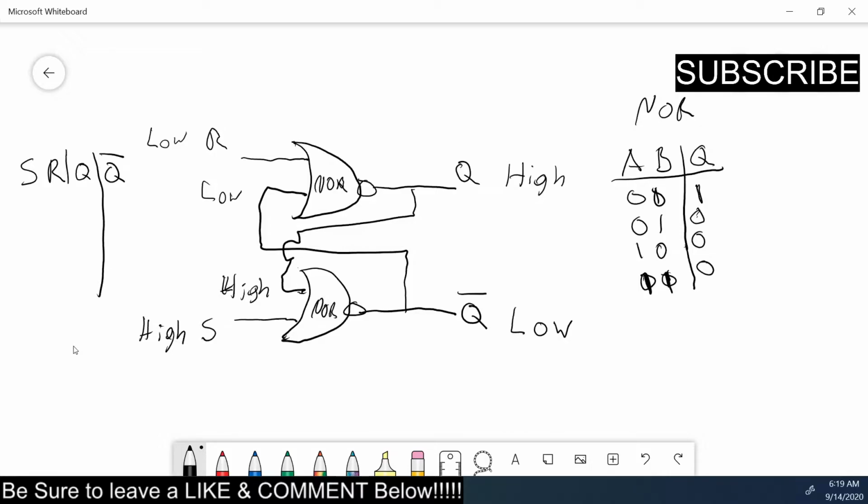Then you have 0, 0, 0, 1, 1, 0, 1, 1. So if both inputs are at a 0, you're going to have last state. So this is going to stay whatever it was. It's going to latch the last value if none of the inputs are high. If reset is high, Q is going to be a 0 and Q naught's going to be a 1. If set is high, Q is going to be a 1 and Q naught's going to be a 0.